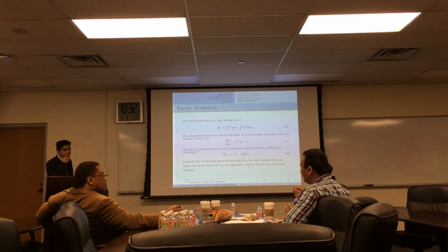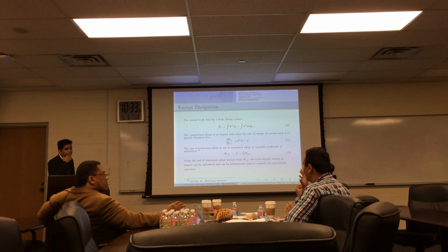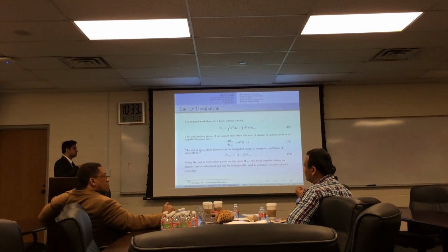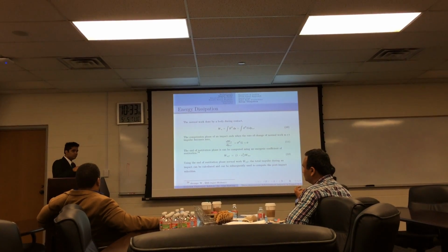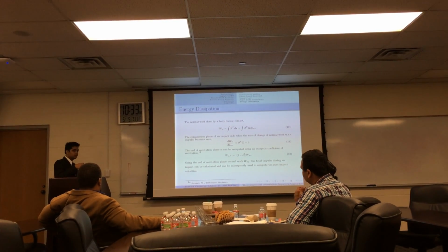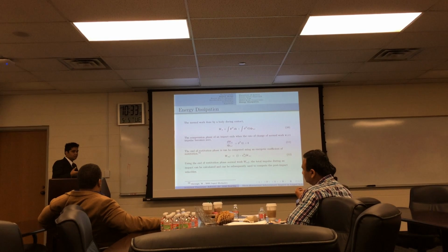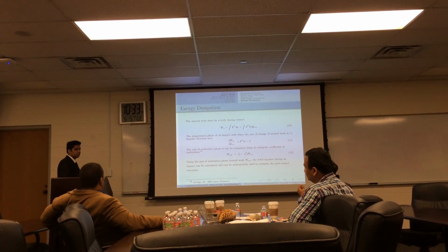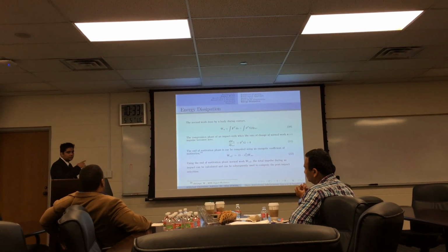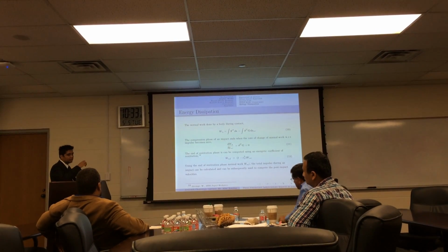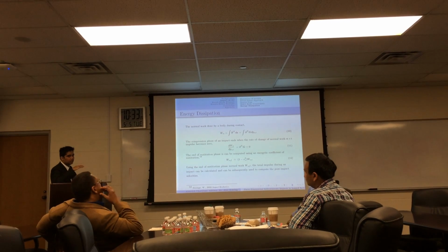Would that be different, or exactly the same solution? If a robot is running, the pre-impact velocities, the velocities that we were considering before, would be higher compared to if something is walking. So based on that, the loss of energy and the impulses over there would change.